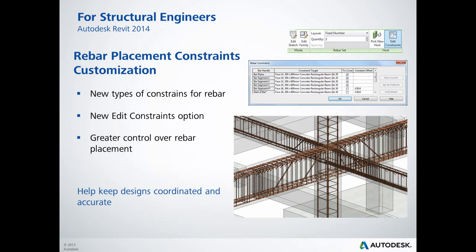Rebar constraints are part of an internal mechanism used to set and lock the geometry of each rebar instance with respect to its concrete host element. In this release, you can now apply overrides to the default host constraint behavior on a selected rebar element. Once you select a rebar, the Edit Constraints option is available. Rebar constraints apply to rebar cover, other rebar instances in the host, and the host surfaces.